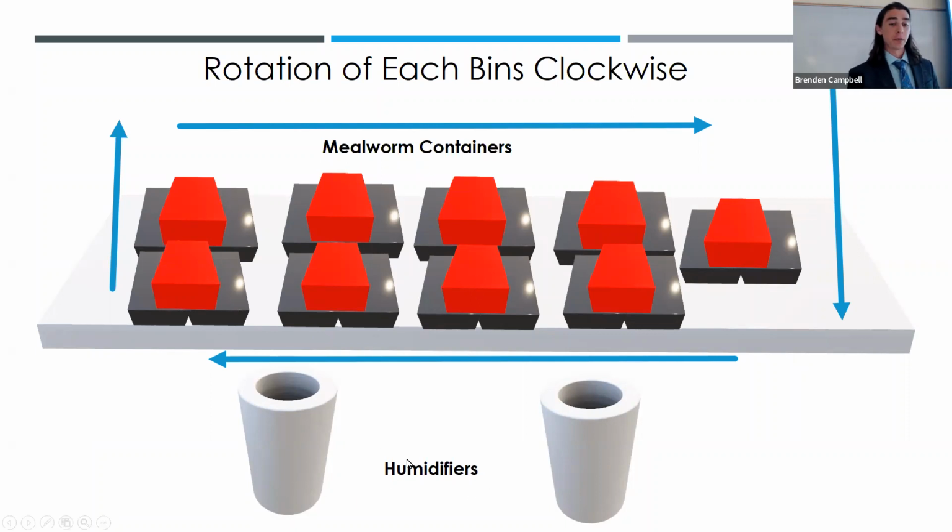The humidifiers are depicted here as they were below the bins in order to create an attempt at optimal humidity and temperature. The humidity did not reach optimal humidity. It only reached between 50% and 55% relative humidity for the average of the entire 300-day period. Temperature was consistent between 77 degrees Fahrenheit and 80 degrees Fahrenheit, or around 23 to 25 degrees Celsius.